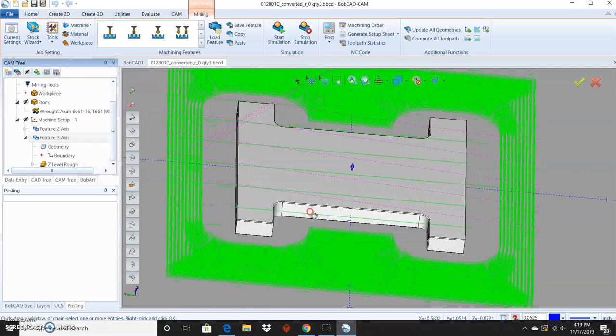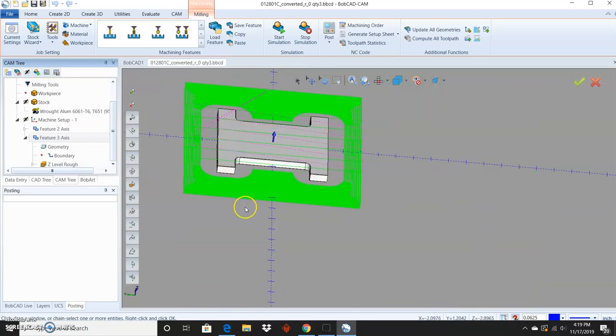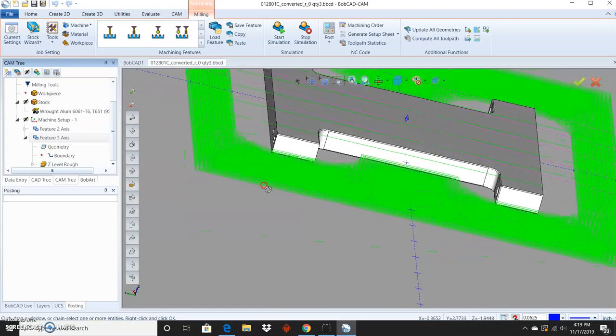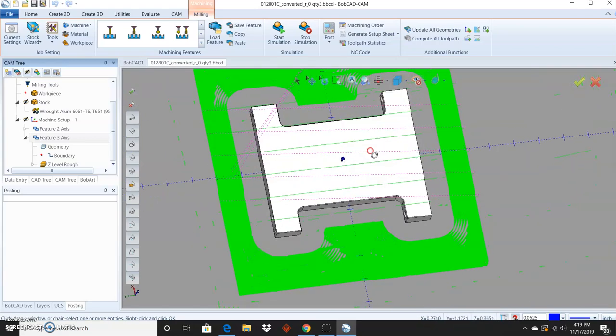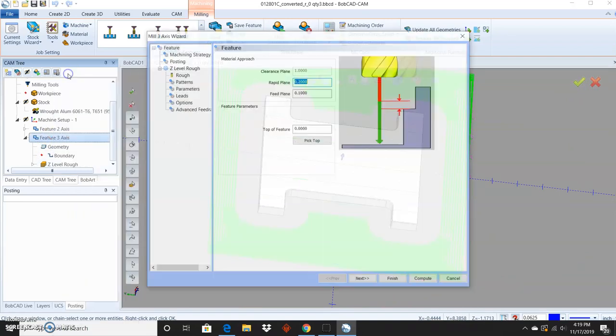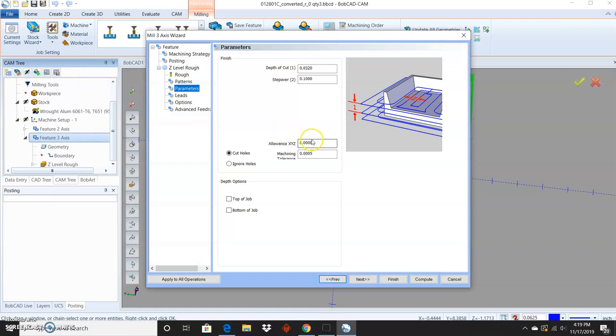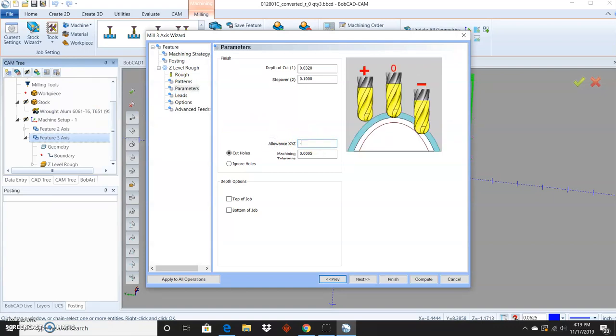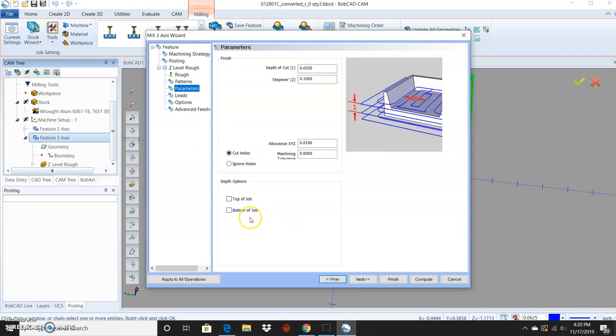And now you can see it's going around the part in a high feed milling sort of application. That's been roughed out, but I didn't leave any material XYZ, so I'll leave 5. Actually, we'll leave 10 on all surfaces. I want to drive that past the bottom of the part. I know my part's half-inch thick, so I'll just say 0.525 to make sure it goes deep enough.